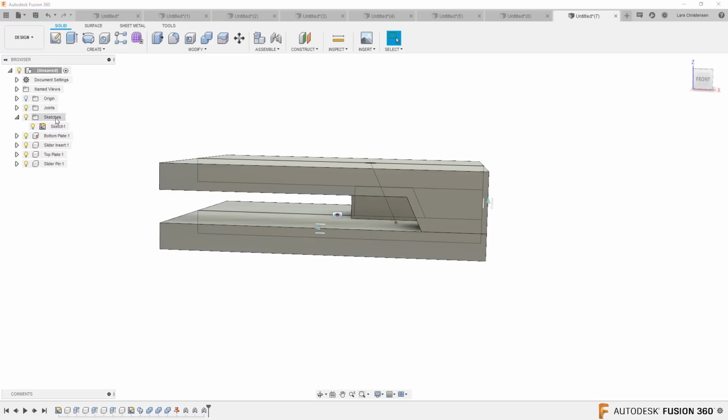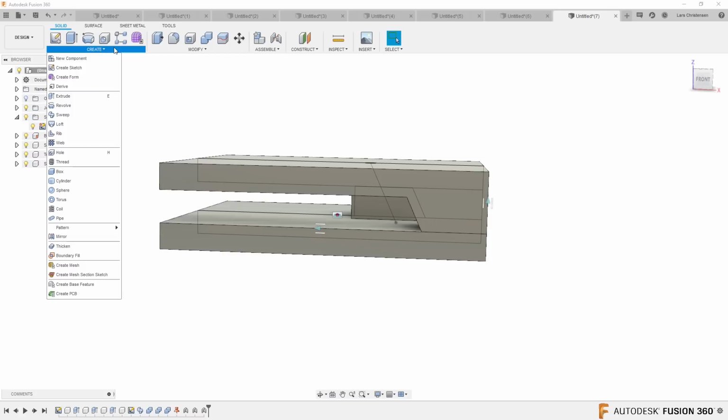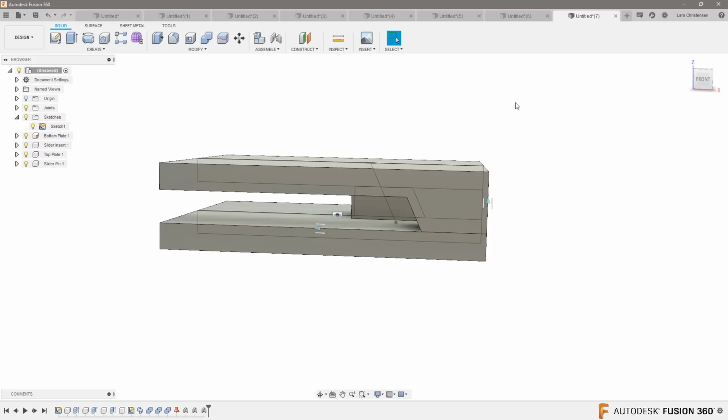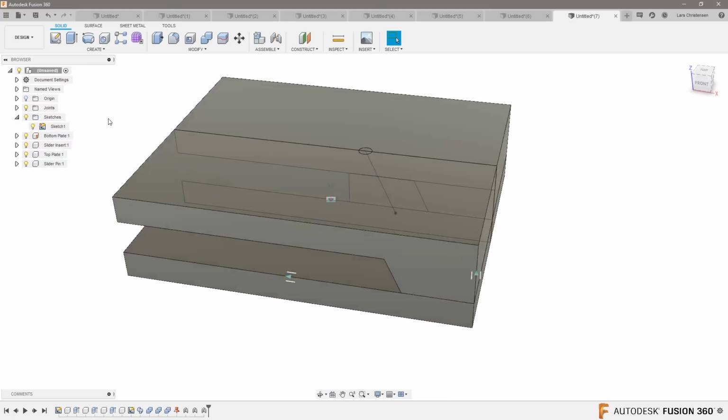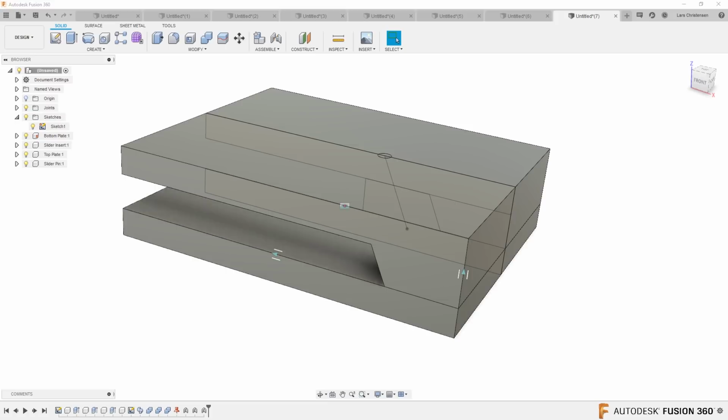So what happens if you are making changes to the sketch? Even if you sketched in one part and brought that into another part, there could definitely be some risk with that. I will bring up that recently in Fusion, we got the derive function in here. It is a great way to bring something forward from a master model, where if you make changes to that, it will not affect what happened behind it. That could be a good option. I'm not going to show that right now. That has been done in other videos. Email me if you want to dig further into that.